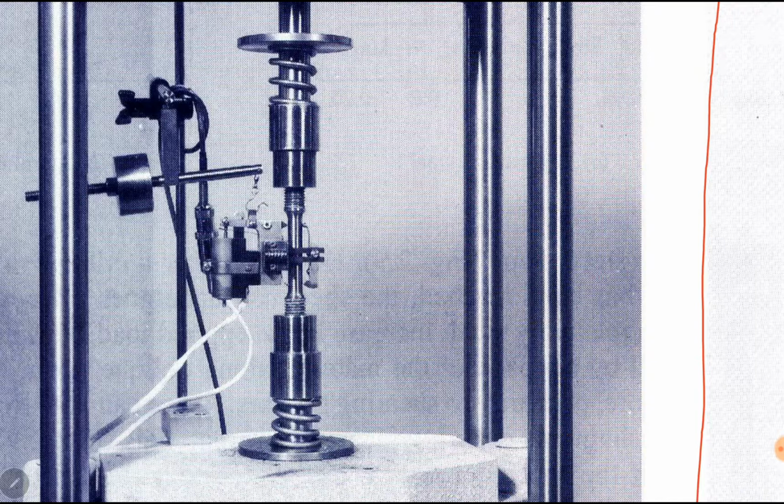At this end we will first produce a section here. Then an area is changed, but also load has been changed, so we have to create a section here. And then another load has been changed at 75 kilopounds, and we have to create a section here. 3 sections we have to create: section 1, section 2, and section 3.